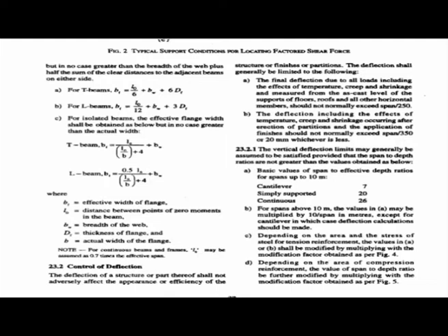Span by depth equal to 20 into 10 by 15, then it becomes 200 by 15, which comes as 13.33.